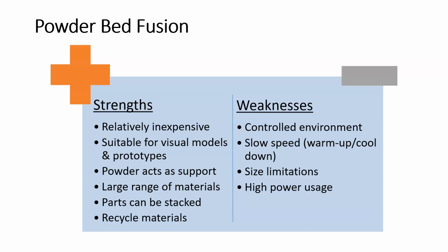So even though the loose powder around the part is not at a sintering or a melting temperature, it still is at a high enough temperature where it's going to degrade the material. And so maybe you have 2 or 3 applications of that powder before you need to get rid of that powder and get new powder in there.